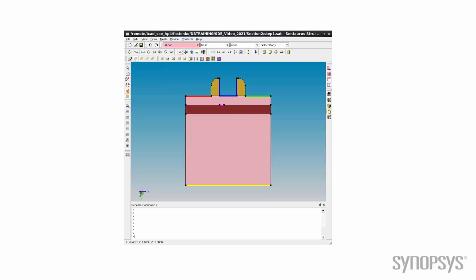Doping profiles are defined on the nodes of the finite difference mesh. Therefore, until the mesh is constructed, we will not be able to see the doping in the structure. At this step, we will only define the doping. It's worth mentioning that natively, Centaurus Structure Editor operates on the boundary only. Mesh generation and doping profile creation is performed seamlessly by Centaurus Mesh using the definition in the structure editor.